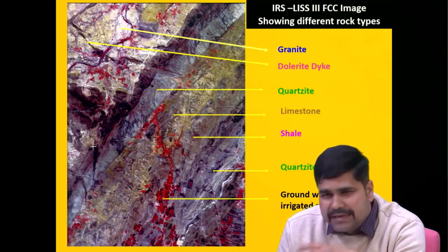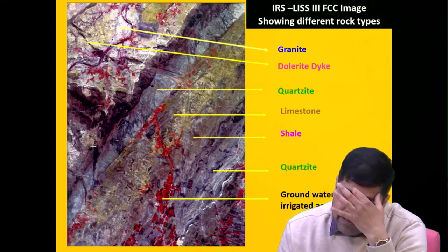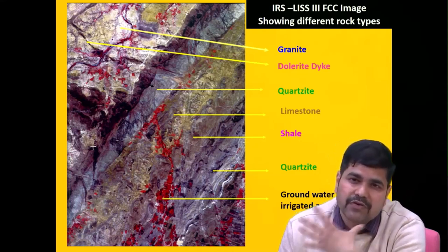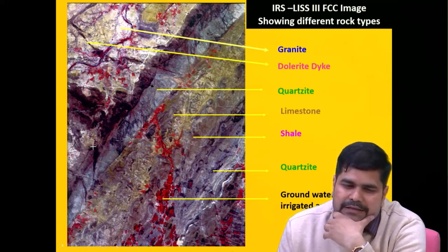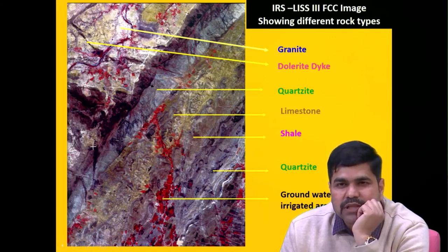Now slightly more detail about the lithology part, because the first thing that you look at, if vegetation is not present there, is the different rock types. So here this whiter patch is granitic rock. Generally granitic is an acidic type of rock where quartz and porous feldspar are present, so that gives you this type of tone and this type of structure.